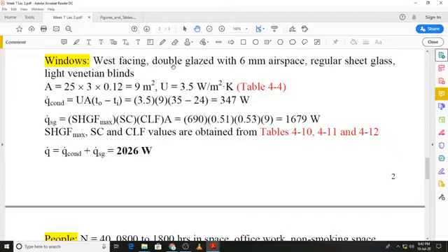And then we read the value of the CLTD under these conditions. The CLTD value is 11 degree C, and that is the value that we have used. Once again, you will use the same formula for finding out the value of CLTD adjusted, which comes out to be 12.5 degree C, and then we move to the heat gain, and I'll go directly to the solution to